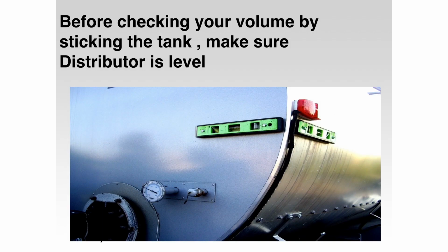Okay? You want to try to keep the truck level or at least at the same plane when you're using that stick. You know, when you're putting it in the manhole, leave it at the same spot. Tanks on trucks are set at an angle a little bit, so we want to make sure if we're checking it at the front of the manhole on our first shot, on our next shot we check it at the front of the manhole also.